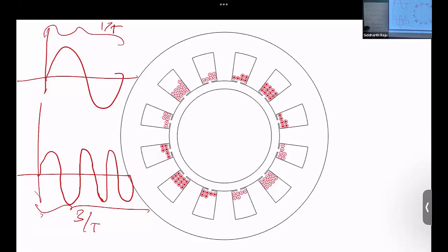So let's say I have a two-pole motor with 50 turns, and I go to a 4-pole motor with the same number of turns, 50 turns total. Will the torque increase? No. You need to increase the turns. To how much? Not sure. Right. So the reason we do go to a higher pole count is because you can get more torque if you can increase the number of turns.